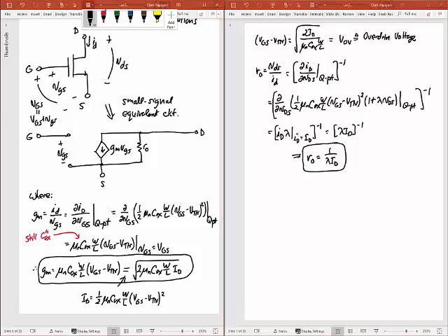But what adds to some of the complexity of MOS, which is already more complex even without this addition, is that in MOS, those aren't the only terminals. I also have a bulk terminal, right, in MOS. And so I can actually have a voltage between the bulk terminal and my source, VBS.